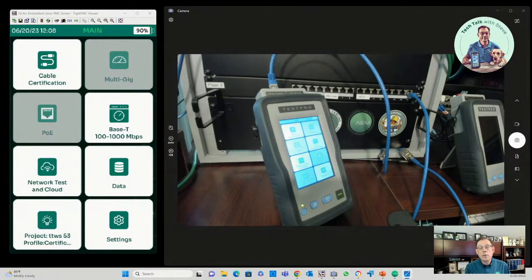When you have equipment at the far end, that's where your grounding happens. So when you install that telecommunications outlet, that faceplate, you don't have to bond that connector in the telecommunications outlet to the building ground system right there. You don't have to take it to a ground lug or a ground bus. Where the grounding happens is when you hook up your equipment, your PC or a server, whatever it is you're going to connect,